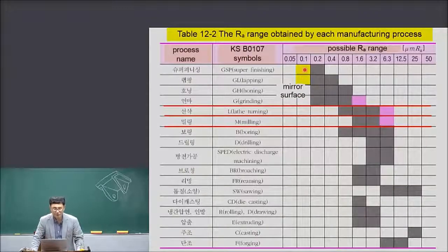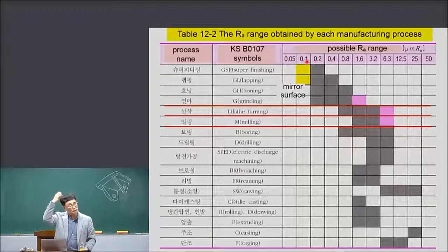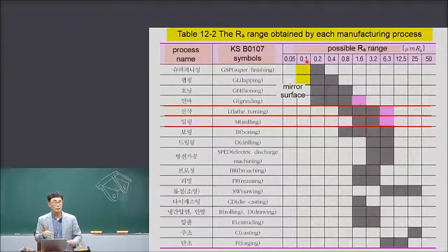Maybe a mirror surface. You can see an image of yourself in the mirror. That means that surface is very, very smooth, and surface roughness is 0.1 micron. The diameter of your hair may be 20 or 30 micron, so 0.1 micron is about 1/200. You divide your hair into 200 pieces, then the length is 0.1 micron.